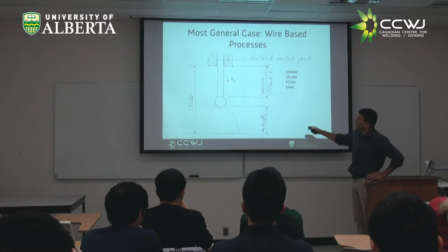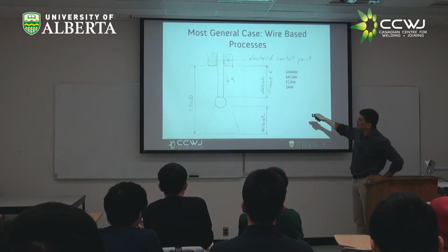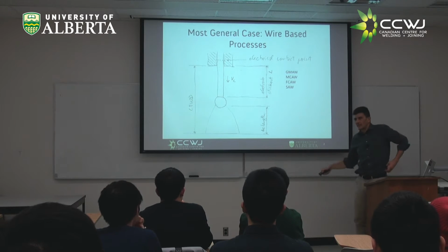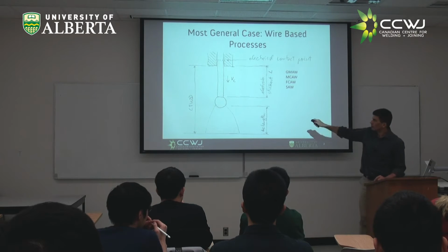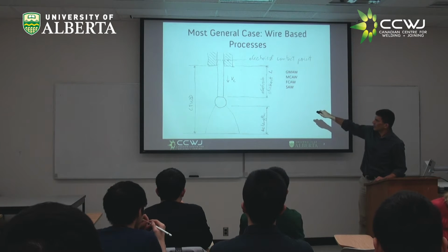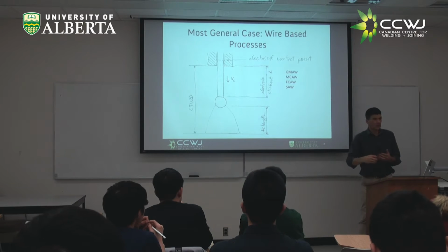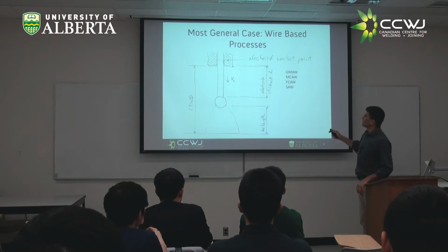Before I get into the voltages, do you remember this drawing we already discussed? Here is the electrode extension or stick out, right? This is what we call the contact tip to workpiece distance. And by the way, just handling this terminology puts you in an amazing place because people get them mixed up. It's not the same to talk about this length from the contact tip to the plate than this length from the contact tip to the end of the electrode. It's very not the same because the implications for the deposition rate, productivity, voltage are very, very different.